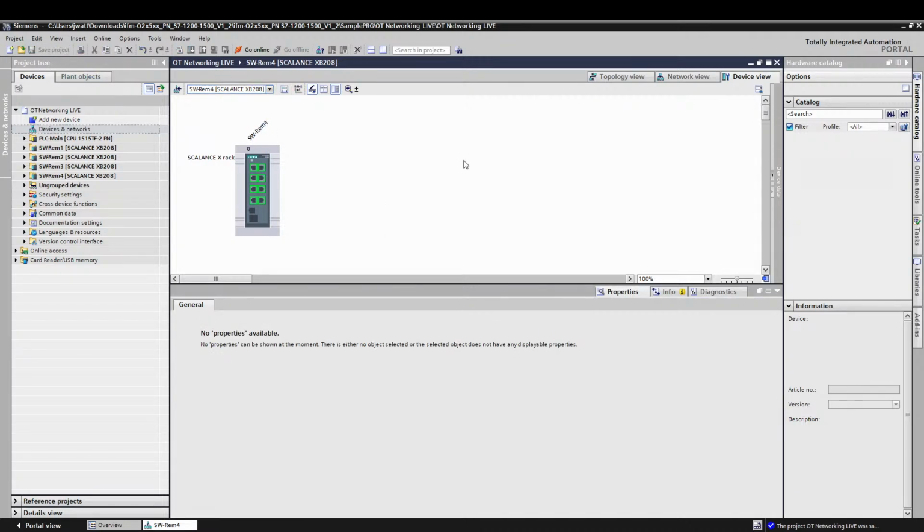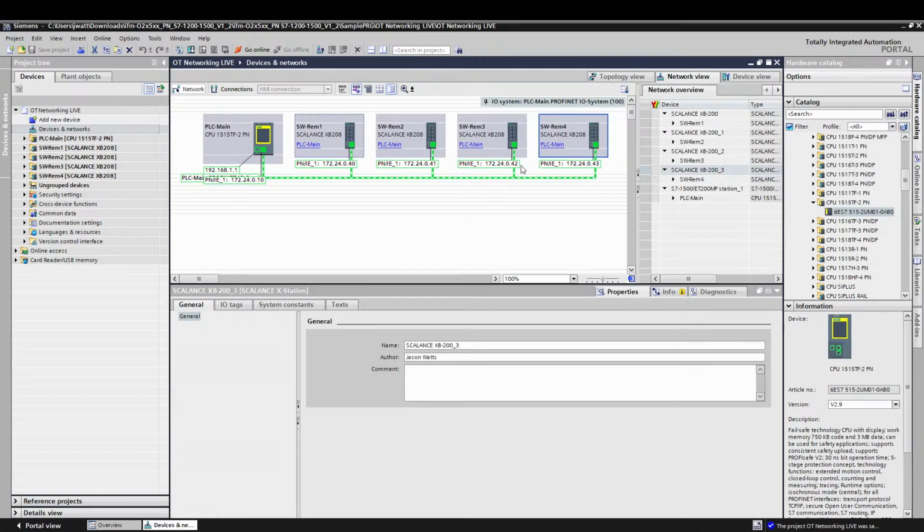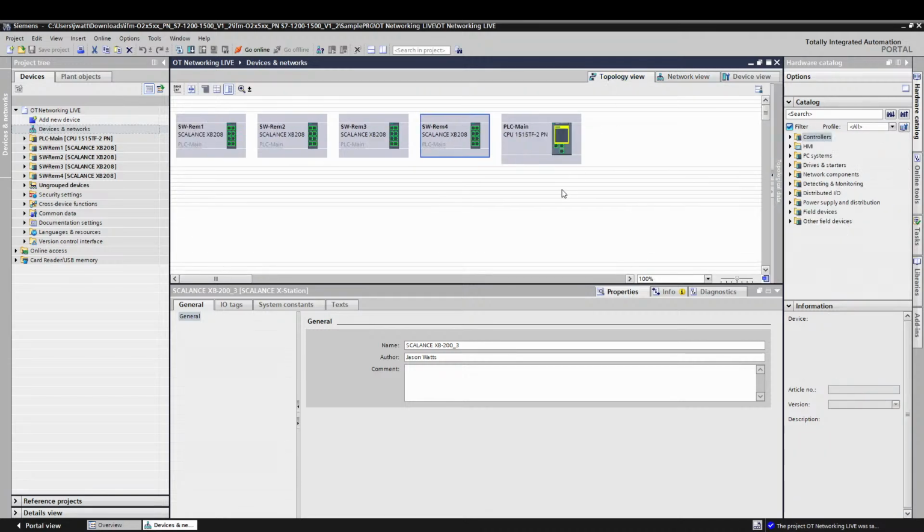And we're done there. So now, if we look at our network view, you notice they look like they're all connected, right? Well, they're not quite connected for MRP. Especially because now that they're actually on Profinet, which, by the way, if you just used the IP address and routing capabilities, these things would work without being on Profinet. You don't have to have a controller. So these can be used as a standard IT network. You don't have to have a PLC. Just letting you know.